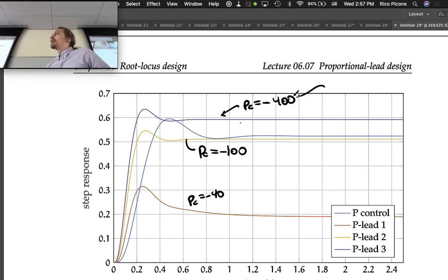It's common that we'll operate in saturation in certain instances for our actuator, but if you do that, the performance is going to suffer. So say you run into that problem here where you're like, oh yeah, put in 5 million newtons, and it's like, well, I only have 500 newtons, so that's what I'll put in.